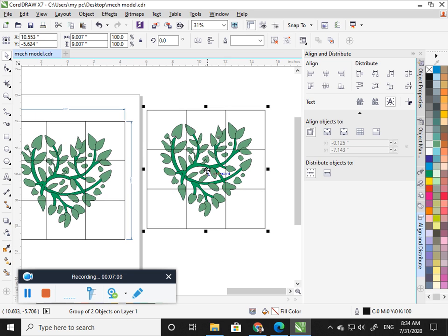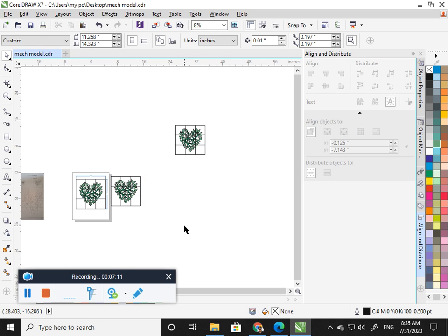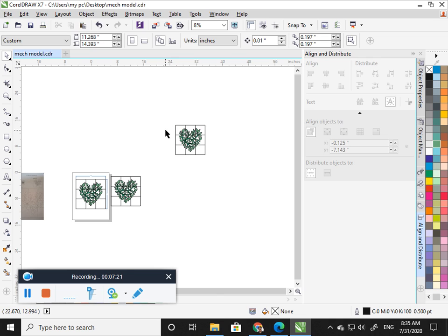Okay, so hold with the left mouse button. One more time I'll explain it. I'm moving this object. Before releasing, just click the right click and release the mouse. So the duplicate will be generated. This is the easiest way of making duplicates. Anyway, the universal tool is copy paste. At any time we can use this, and by clicking the plus symbol also you can make duplicates. Control D also makes duplicates. So there are a lot of ways, and you can use any one.